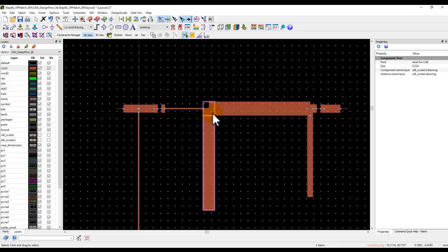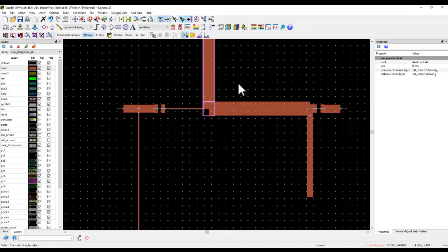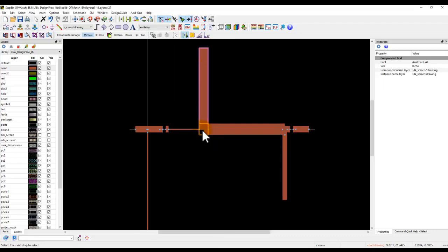So you can take that in case they are coming very close, and you could just use shift X or shift Y to mirror. So just press shift X, which is a shortcut for mirroring it around the X axis. Click on a reference point, and you can just rotate that guy. So you can have one stub on that side, one stub on this side, and then there will be no parasitic coupling between them.